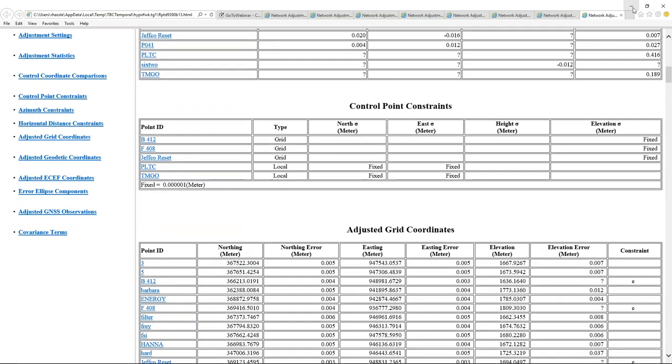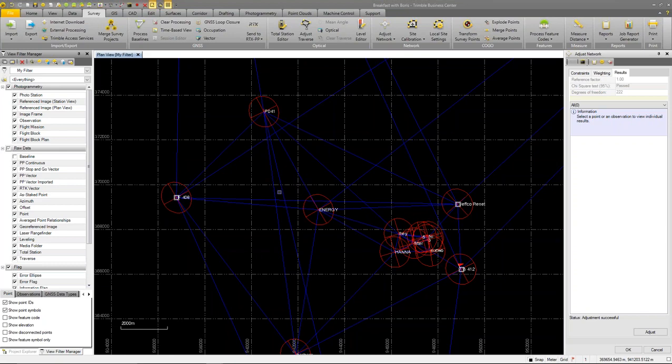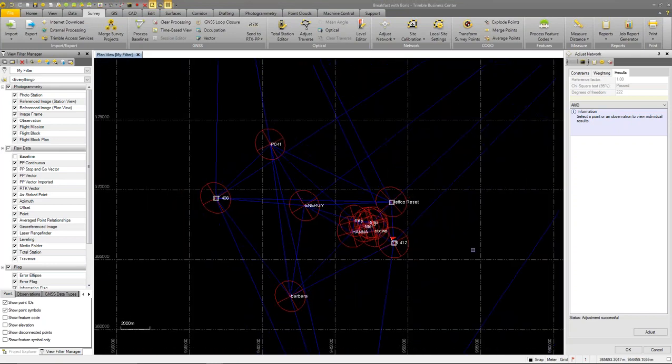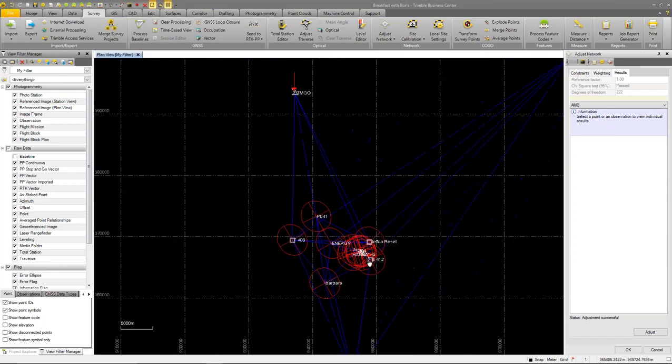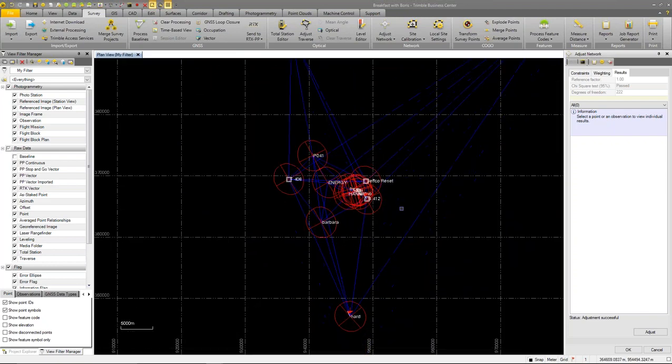I'm tying my vertical control here to my local elevations in the project area, and the tilts provided by that actually make those really far away points not match all that well. It's rare you're going to get ellipsoid heights over tens of kilometers that match with elevations possibly from a different agency in the project area.